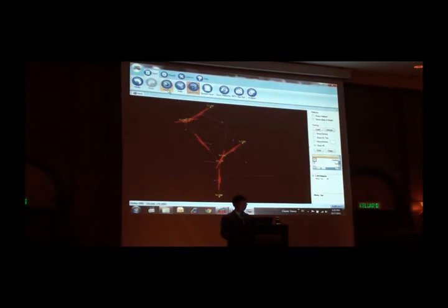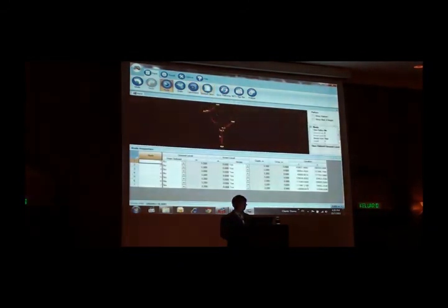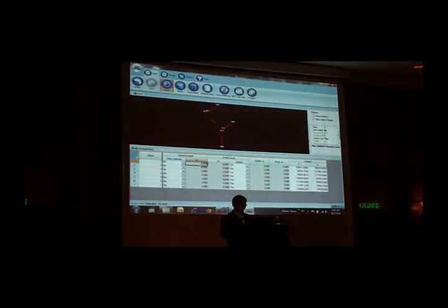Okay, so we can go to the spread input. Okay, so the ground level is automatically picked up. Just now our road level is 3.2, the internal road. It's not the highway. Highway will have a different value. So for the internal road I preset to 3.2, so it is automatically imported.